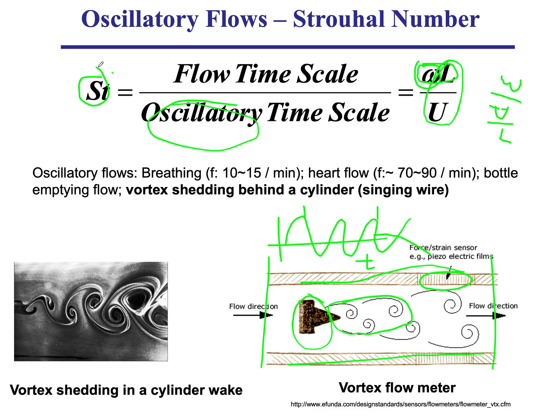if we know something about the Strouhal number, if I measure the frequency, I know the Strouhal number, and I know the diameter of the pipe, then I can get the flow velocity. And if I know the diameter, I can get a flow rate. So this is what we call a vortex flow meter. It's based on this oscillatory behavior of fluids. So you see now we're talking about actual real-life fluid mechanics that you can actually take to the bank, and use in your various engineering problems.